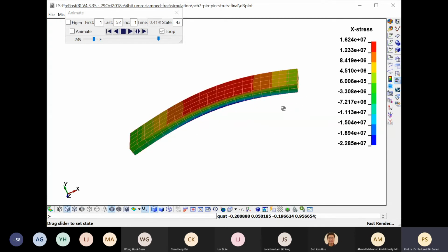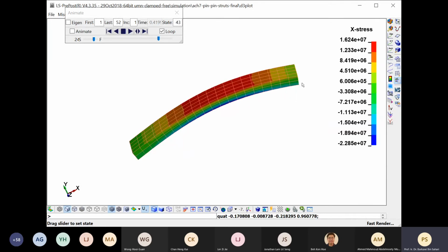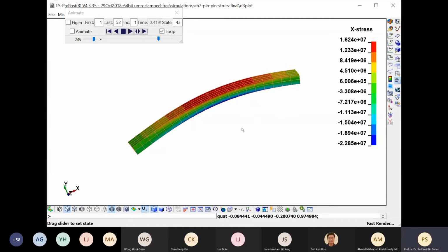Okay, so effective length LE for pin support will be the distance between pin to pin on this beam, which is the length of the column. So that's the first one.